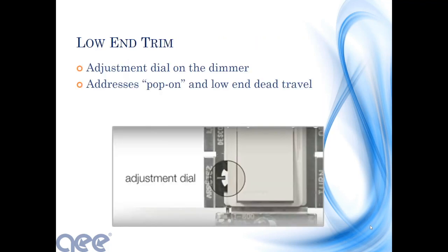And then, one of the other things to address adding load to a circuit, that technology means that now you can use that dimmer with only 1 watt of load. That was one of the problems earlier with the traditional dimmers: you would put the LEDs on, and the dimmer needed 60 watts of load in order for the electronics to function. So you do an energy project where you put in a bunch of LEDs and then you add an incandescent dimmer just to load so the dimmer would work. That's where the technology has addressed that.